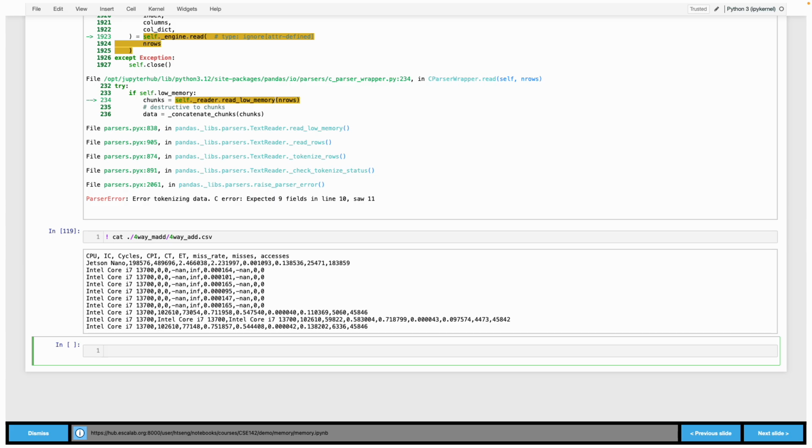And in the meantime, here I also have stats from the Jetson Nano. It's kind of interesting. Why am I saying that the cache miss rate reported by the Jetson Nano is not trustworthy? Because here on the Jetson Nano, we got a cache miss rate also around 14%. However, if you look at its CPI, it's 2.5. Typically, if you have a pretty smooth pipeline, your CPI should be pretty close to 1, and most of the time lower than 1, because right now we are able to execute multiple instructions at the same time. However, here it says that on average you have to spend 2.5 cycles, and you only have a 13% miss rate. If you do the math, you will figure out that's not reasonable. So that's why I'm saying the performance counter of the Jetson Nano is not that trustworthy. But for this, at least you should know that our estimation is actually pretty close to reality.